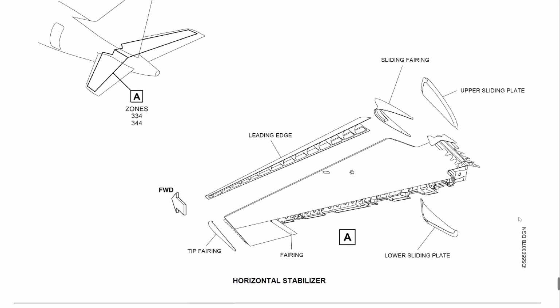And do you remember, we have these openings of the rear fuselage because the forward and the aft area of the entire horizontal stabilizer is moving. And because it's moving, we need enough space, an opening which is big enough to provide this movement of the horizontal stabilizer. But we don't want the airflow to go inside the compartment. We have to protect it.